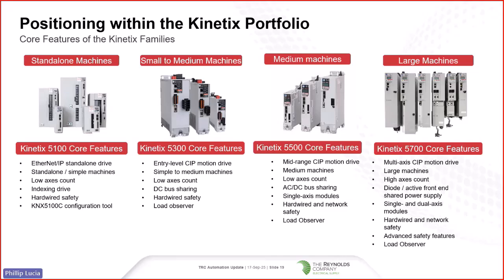The Kinetics 5100 now is a standalone EtherNet/IP single axis indexing drive. This means it does not require or use the integrated motion features of the Rockwell ControlLogix and CompactLogix PLCs. In fact, the 5100 can be used with a Micro series controller or without any controller at all. But the 5100 does provide lower performance, and it lacks certain features, like multi-axis coordinated motion, most importantly.